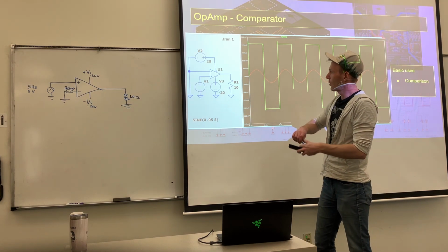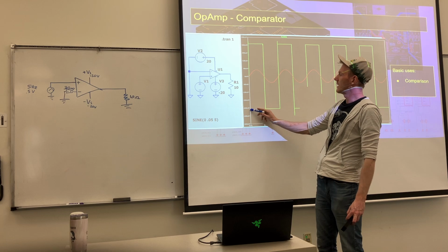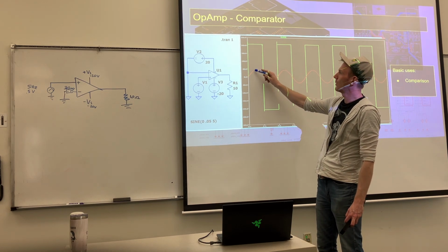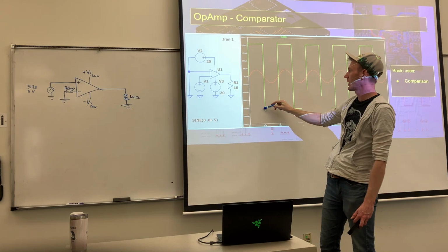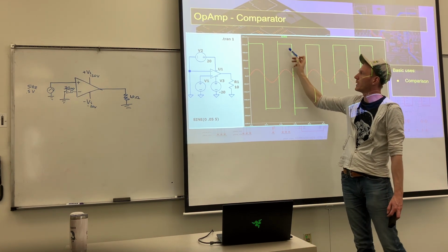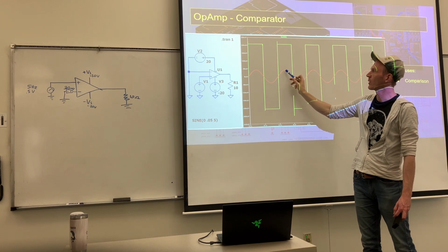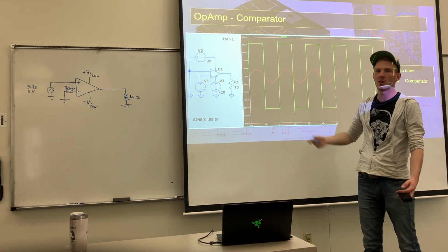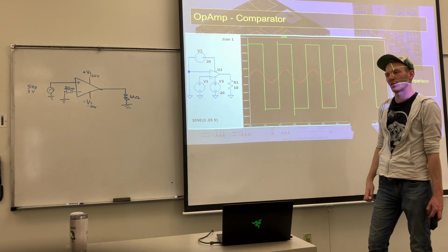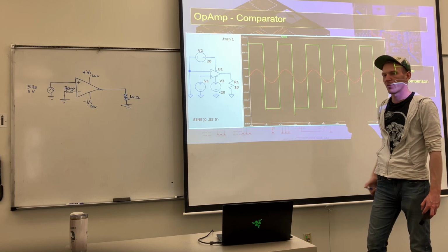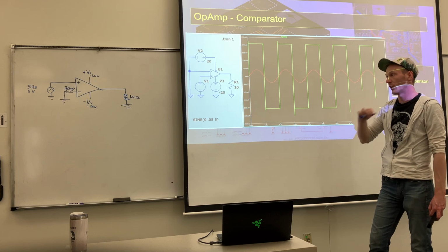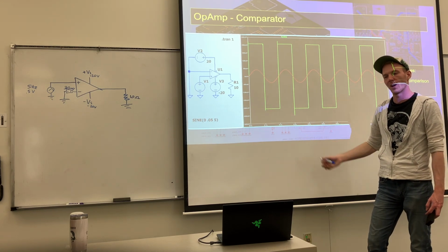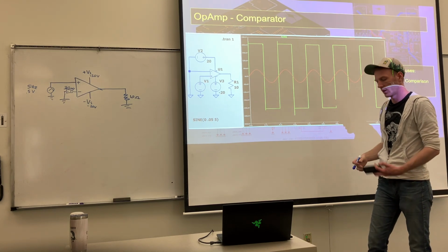Right. Okay. So if you can imagine this, it would be negative, negative, negative, and as soon as the sine wave hits 30 millivolts, jump up, very narrow peak, and all of these peaks would narrow to just the points where this hits 30 millivolts. Based on the shape of the sine wave, these would be like half the width. Well, okay, that's a nice convenient way of establishing a square wave or rectangle wave technically, right, that is not the same sizes anymore.